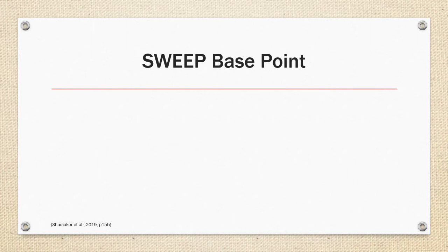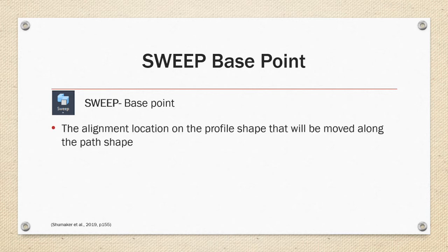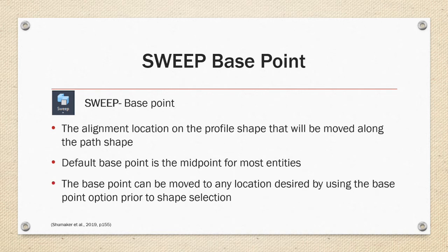Sweep base point. The sweep command in AutoCAD includes different options for setting the base point for profile shapes, the alignment location on the profile shape that will be moved along the path shape. The default base point is the midpoint for most entities, and the base point can be moved to any location desired by using the base point option prior to shape selection.